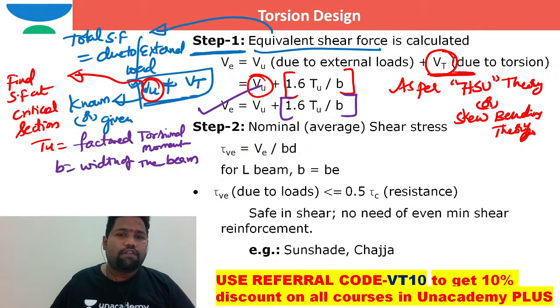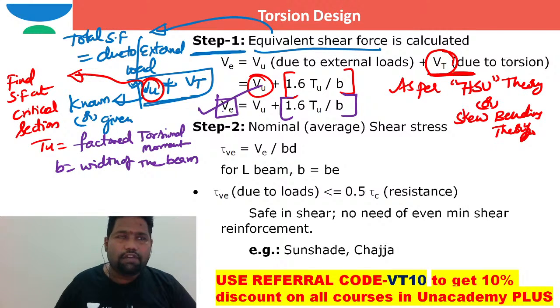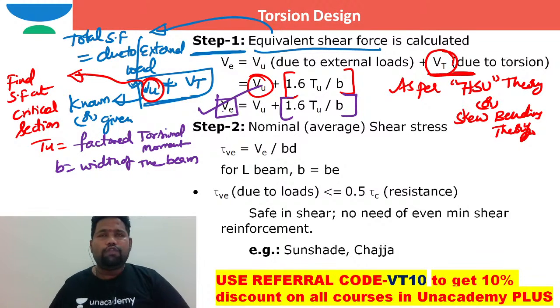After you work out the equivalent shear force, first of all, you need to design for shear. To design for shear, first I worked out the equivalent shear force for which I need to design the shear reinforcement. After I work out that one, the remaining steps are just like that of limit state of shear only. In limit state of shear, after you work out the shear force, you will make a comparison between tau v and tau c.